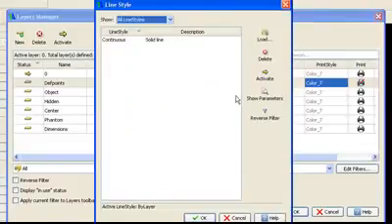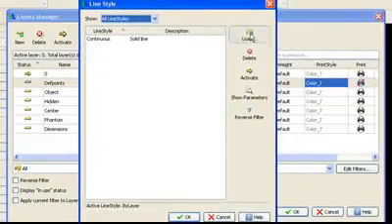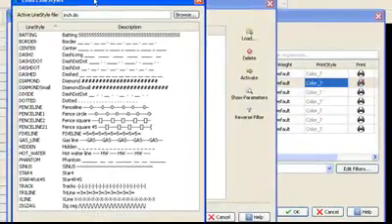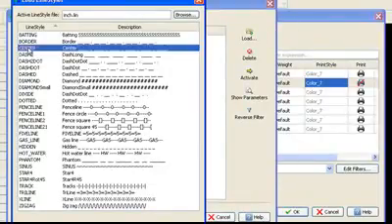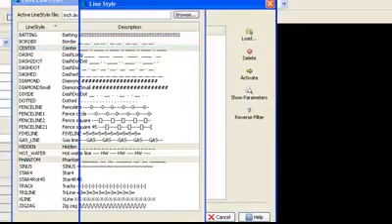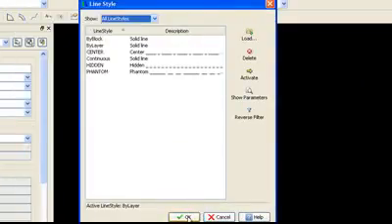All I'm going to be doing right now is loading in my line styles. That's it. I'm not going to be assigning them to a layer. I just need to go into the Line Style Load menu and pick the ones that I'd like. So the ones I think I need are going to be center, hidden. If I hold the control key down, I can select multiple line styles, and then I would like phantom. Okay.